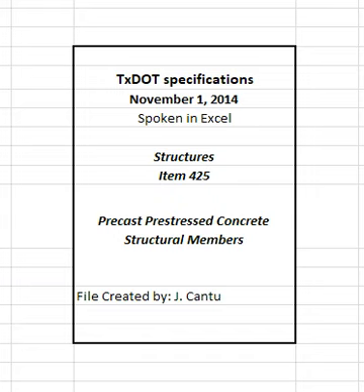2.1 Prestressing hardware. Furnish prestressing hardware that meets the manufacturer's specifications. 2.2 Concrete. Furnish concrete of the class shown on the plans. 2.3 Prestressing steel. Furnish prestressing steel conforming to one of the following types. 7-wire steel strand meeting DMS 4500, Steel Strand, Uncoated 7-Wire Stress-Relieved and Low-Relaxation for Prestressed Concrete. Alloy bars meeting ASTM A722, or steel wire meeting ASTM A421.